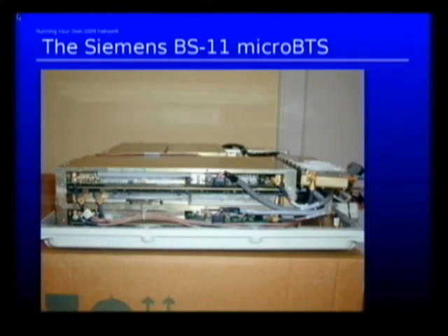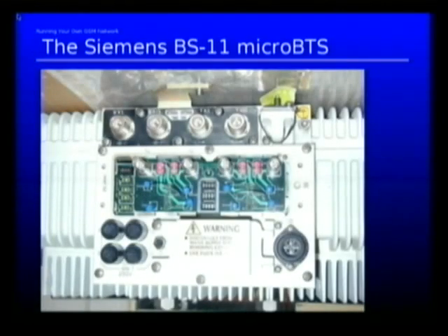This is again from the side. You can see more shielded boxes and SMA connectors, coaxial wires and serial lines. This is the connector panel where you actually connect the transceiver. RX1 and RX0 are the two receive antennas. TX1 and TX0 are the transmit antennas. Those fancy twin-ax connectors are for the E1 line, the four you have here. Then you have a couple of jumpers and auxiliary connectors. And this guy at the bottom is the power connection. Yeah, 4-pin power. Amazing. It's just regular AC power. Nothing fancy. It's just a connector that is fancy.